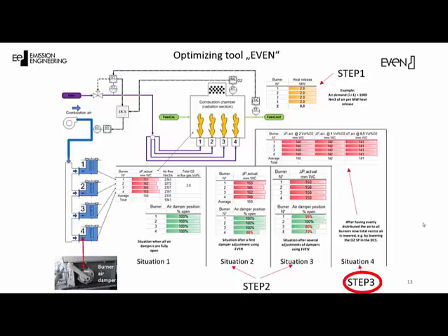In Step 3, the total combustion airflow is reduced, either by changing the set point for the oxygen target in the DCS or by adjusting the excess air factor in the fuel-to-air ratio control loop. In Situation 4, you can see the results once the volume percent of oxygen is reduced to 2 or 1.